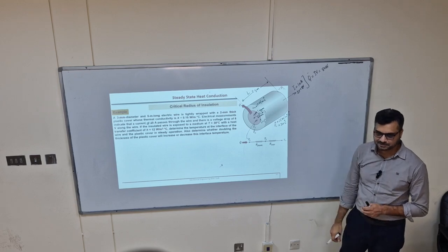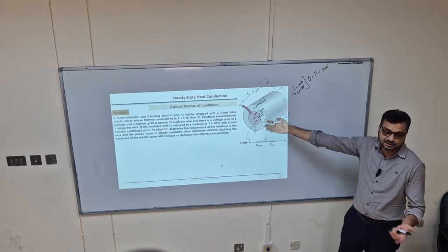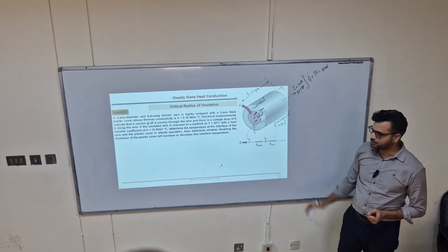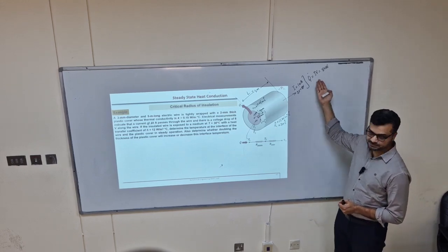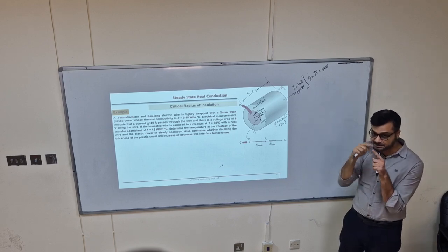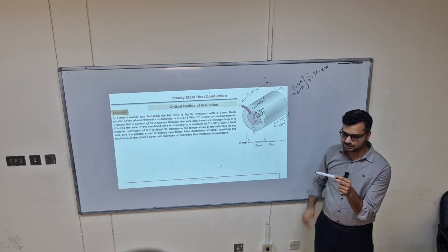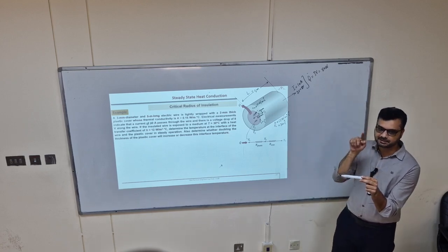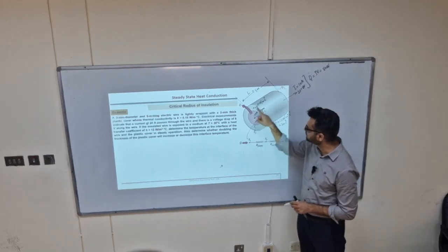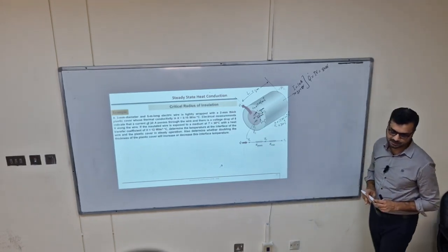Okay. So thermal conductivity of the wire, why do we need it? Because this wire is producing this much heat because of this current and voltage. Now this heat is flowing from the outer surface of the wire towards the outside. So from this wire onwards, whatever is the thermal conductivity, that will count, for how much heat will flow now.